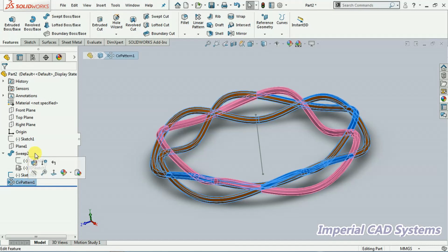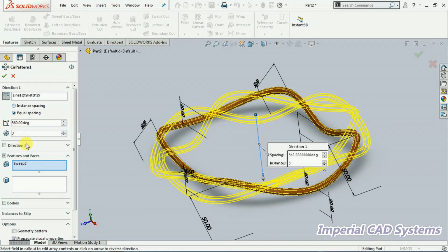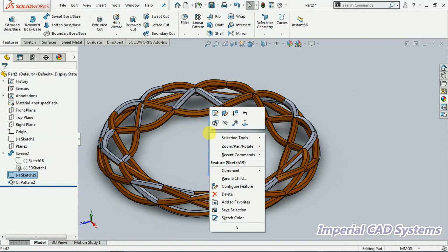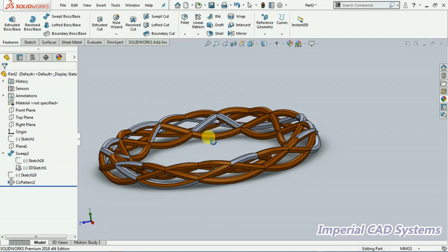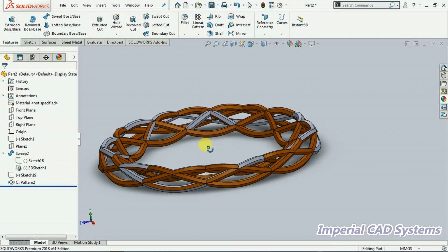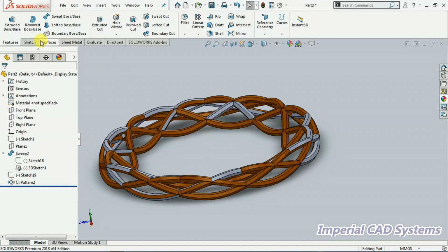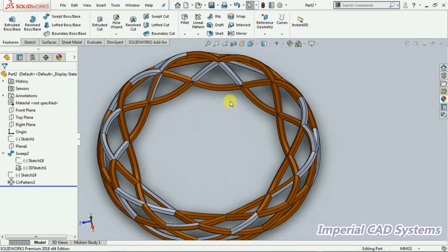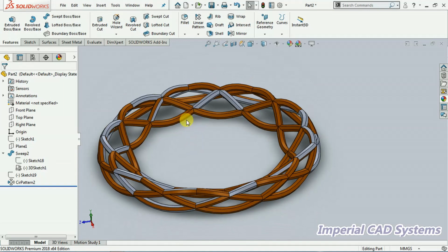Now I go to edit. Now I increase this to 6, then go for OK. And we can hide this axis, as this line we took for reference, for the axis of rotation. So this output we can generate by 3D curves, by going into 3D sketch, and inside we can create a circle and we can generate a surface to show the base.